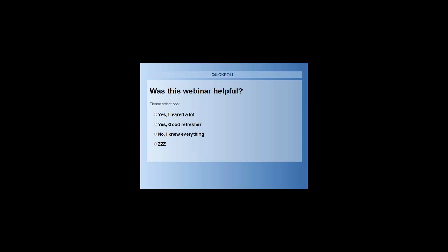Well, that's a real good question. Certainly one of the things I think that has been very helpful is the use of the retroreflective backplates. That wasn't on the list, I don't think, but let's see. Yeah, I've got it up in front of me now. To reduce the rear-end collisions at signalized intersections, adding a lane typically isn't going to help a whole lot.